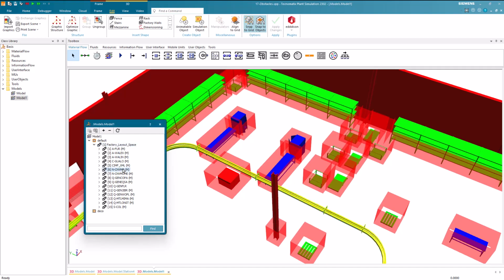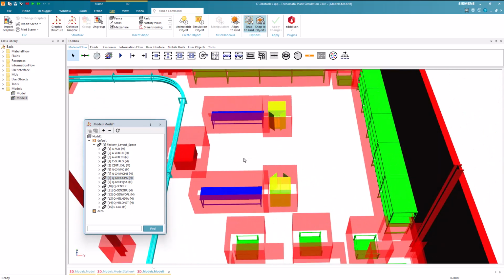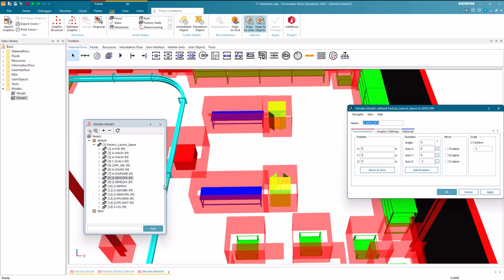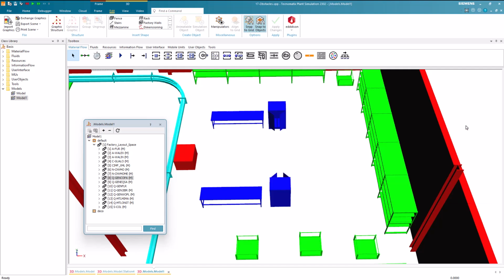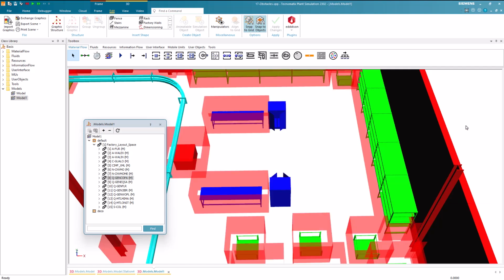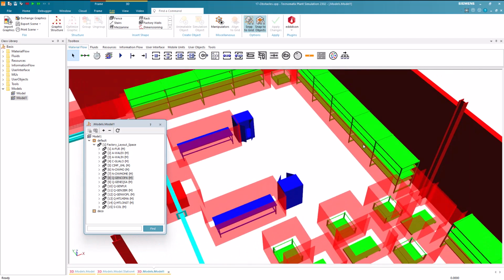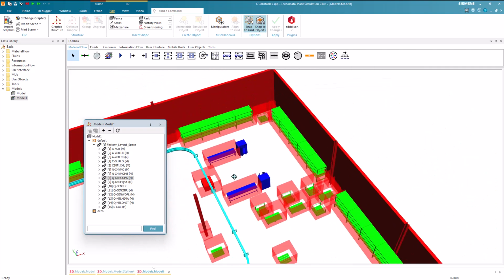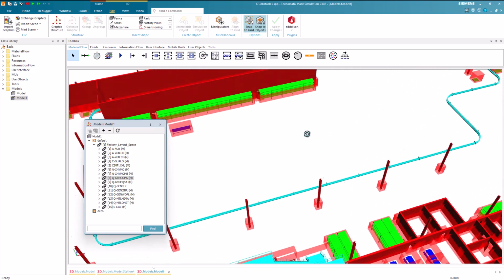Let's assume that we do not want the shelves, which are the 8th object, to be an obstacle. Then we could select them and open their Edit 3D Properties window. In the graphic settings, we could now set the obstacle to none. If we now show the obstacles again, we can see that they are no obstacle. As you may notice, the suspension railroad is also no obstacle. The reason is that it is higher than 2 meters, which can be looked up in the Edit 3D Properties window.